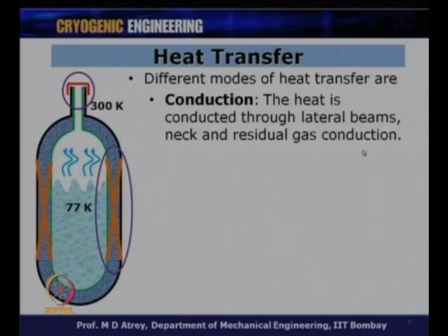Also, we have residual gas conduction. Many times we will have vacuum between this inner vessel and outer vessel, but still, depending on the level of vacuum we have, we will always have some residual gas over here. And this residual gas will cause residual gas conduction, although it will be minimized depending on the vacuum levels we are talking about.